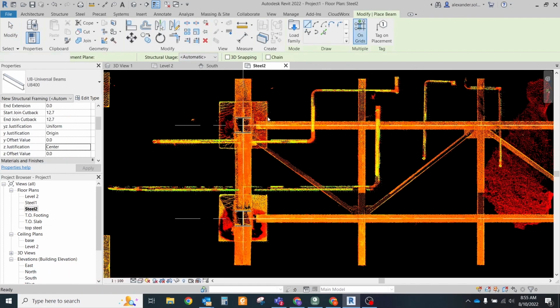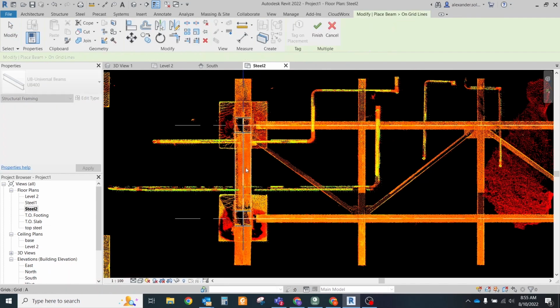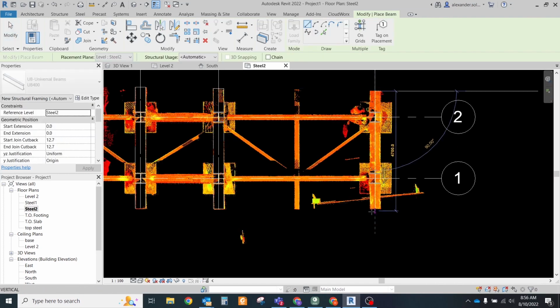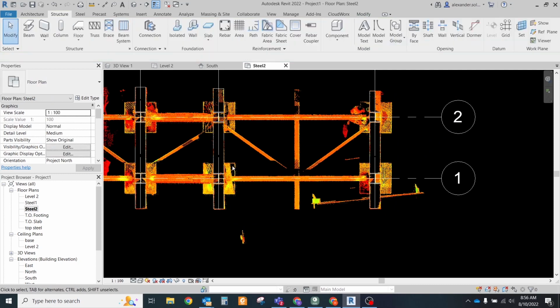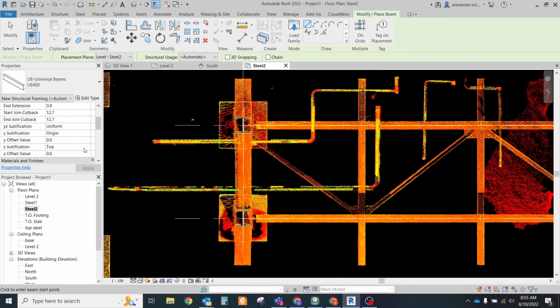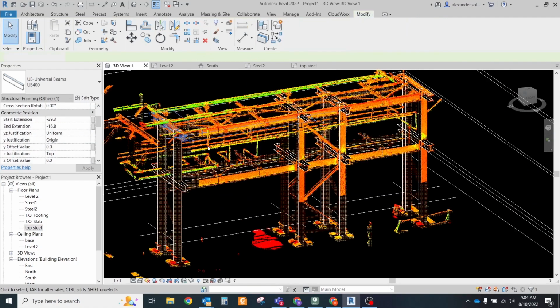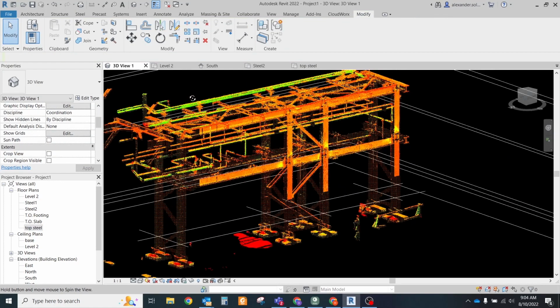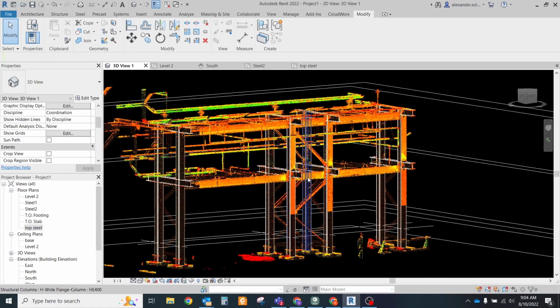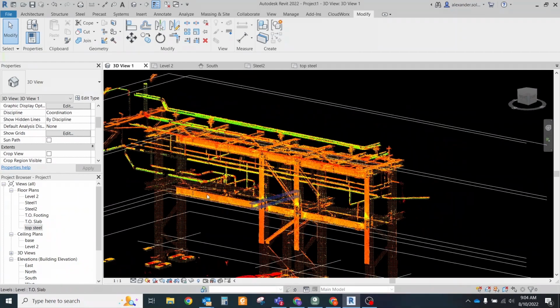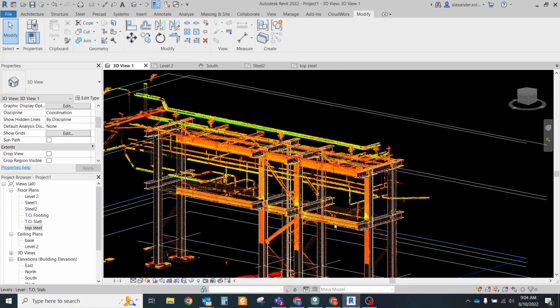Go to the relevant floor plan, structure menu and select the beam tool. To place multiple beams, you could use the on-grid tool, and for placing only one element, you could draw it manually. And don't forget that you should set the correct elevation level and choose the right placement order. In my case, I set the elevation level on the top of the beam element. That's why I specified justification by Z at top and stick symbol location was also top of geometry.